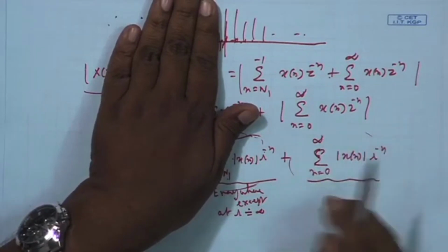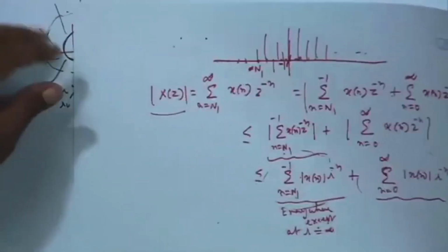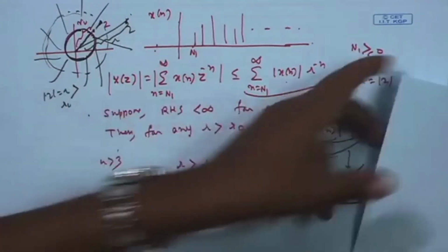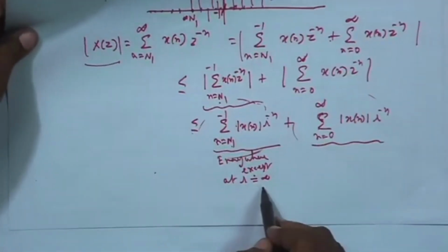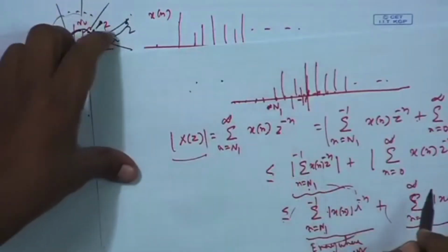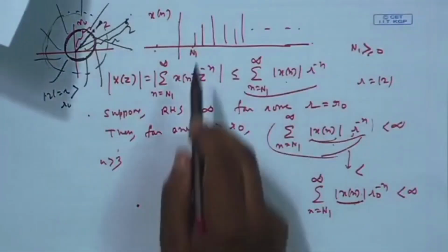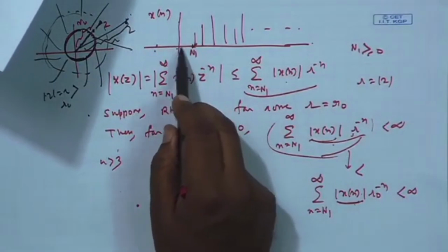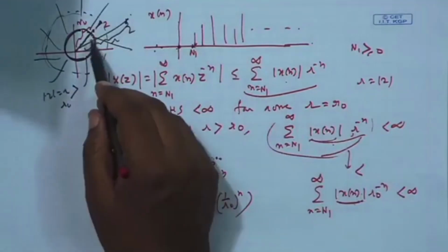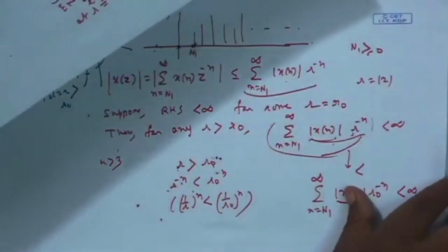The z transform exists, and the region of convergence is what? Outside a circle, up to infinity, and if this part is present, infinity is not allowed. So, overall, yes, outside a circle, but excluding z equal to infinity, r equal to infinity. In the case where it starts at n 1 to the right of the origin or at the origin, not at a negative index, it converges outside some circle and goes up to infinity. Okay. This is for the right sided sequences.